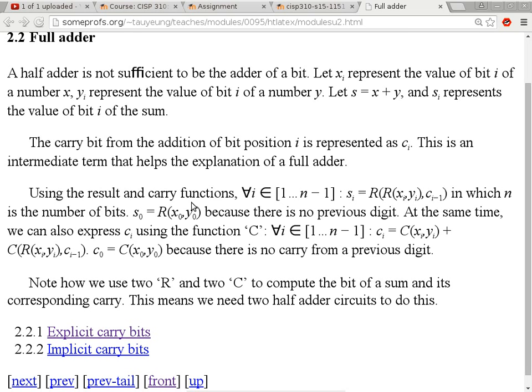The question is, is that the actual answer? Not until you leave enough time for this guy to settle first, and then the output of this makes this guy settle, the output of this makes this guy settle, and so on, until you leave enough time for all of that to propagate all the way to the most significant digit. The output of the most significant digit and also the sum of the most significant bit is unreliable. They will basically keep changing state because it's using partial answers from the previous gates. Okay, so it's basically some time function from all the stuff you're talking about. Right. The propagation, and that's how you build a circuit.